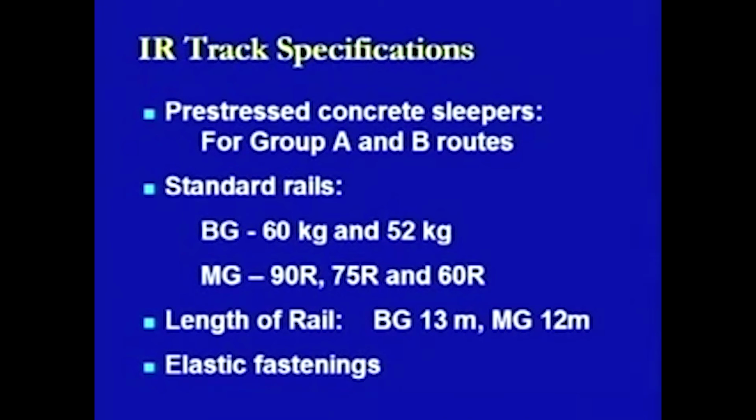Another important thing is the fastenings which need to be provided. Fastenings means those things which are used to connect the different rail sections with each other or the rail sections with the sleepers. These fastenings should be elastic in nature, that is, as far as possible we should use those fastenings where the elasticity is maintained.